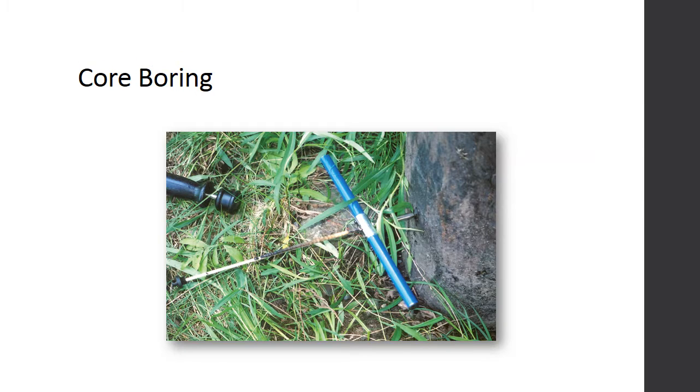Increment core borings of representative areas should be taken perpendicular to the face of the member being sampled. All test holes must be plugged immediately after extracting the increment core with a tight-fitting wood plug treated with a preservative similar in performance to the member being sampled.